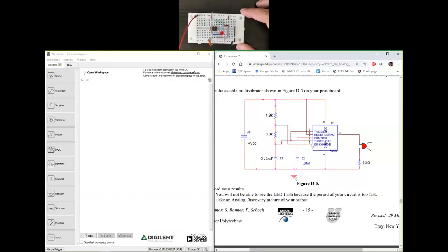So what is fascinating to me, actually that's the first thing that fascinated me about this 555 timer, is that the input is constant, 5 volts, 9 volts, any voltage between 5 and 15 volts. It does not change with time. So the input to this is a constant DC voltage, but the output keeps going between low and high. It's an AC signal. So the fact that we can generate that by using a capacitor charge and discharge cycle, that is what attracted me to this.